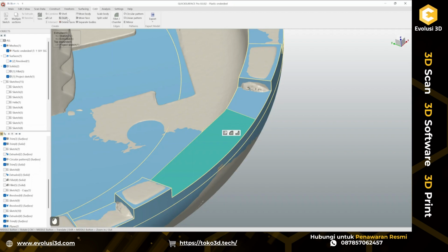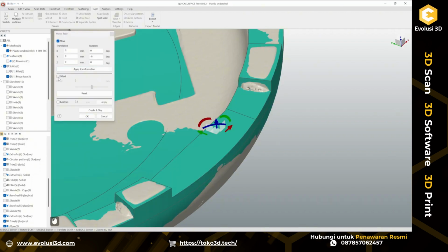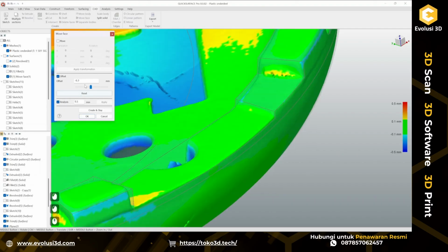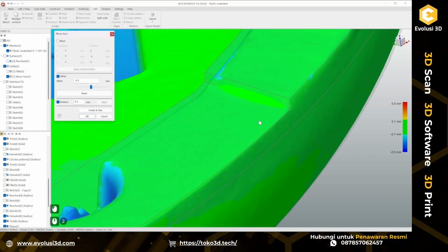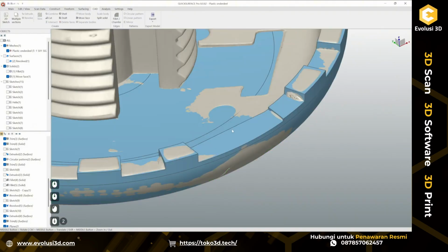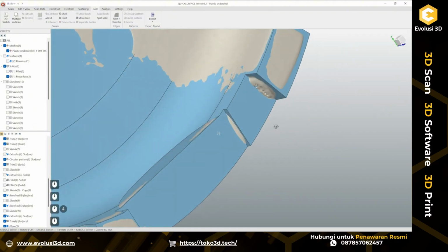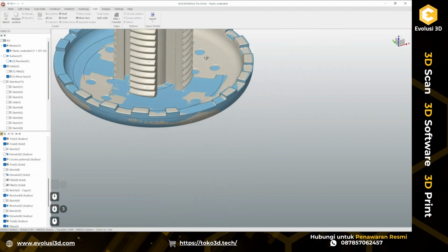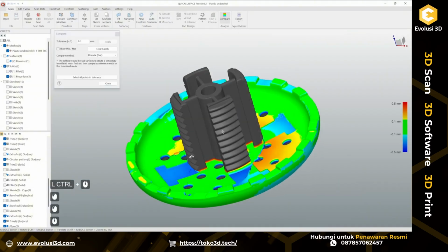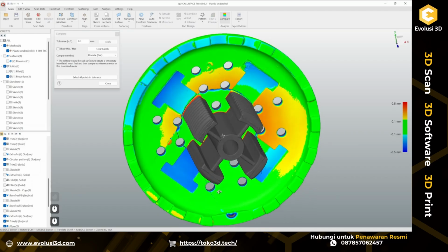And now I can actually go to move face command, probably with offset. And let's just try to move it slightly, like 0.2 millimeters. Okay, good. So, well, this worked out actually. Okay, so perfect. We're quite close everywhere, and I just have a couple more steps to do on this part.